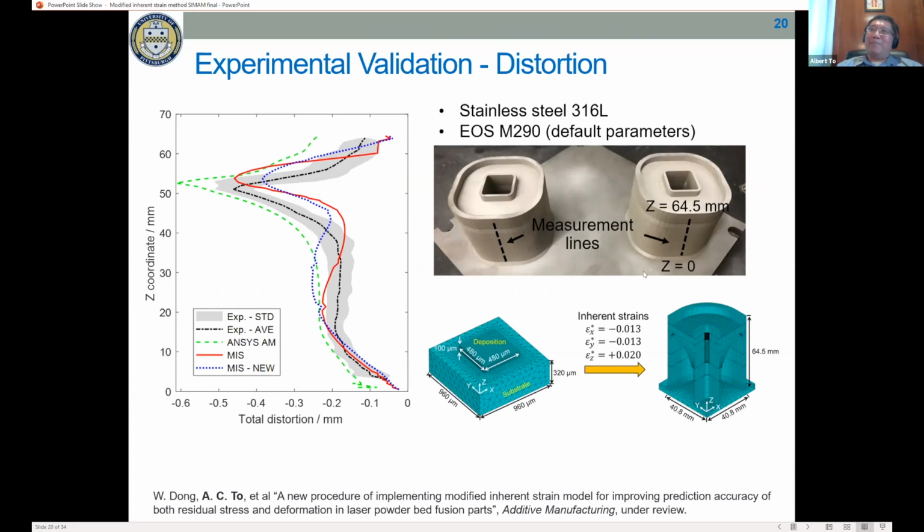Initially it has a thin wall going up, and then as it is going up, it becomes an overhang that is also changing in wall thickness. As it's converging, there's obviously lots of distortion at the point when it converges. This is a good part that many people use to compare to their part scale distortion model.